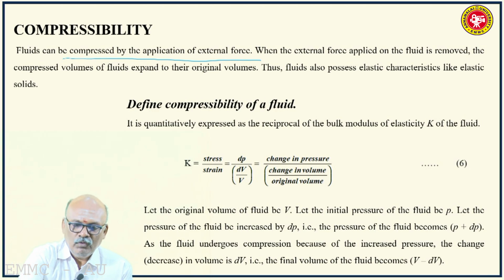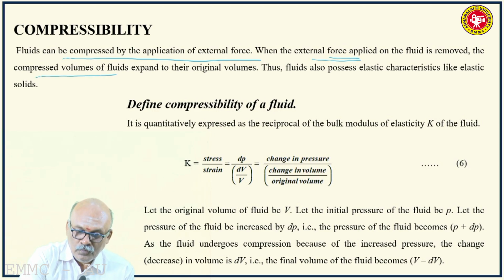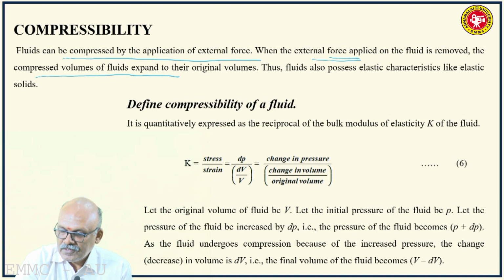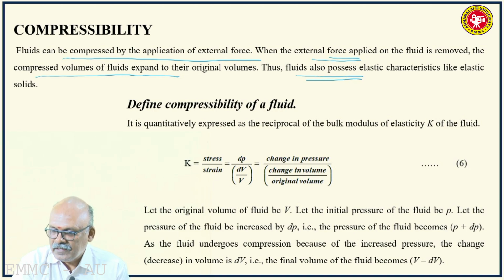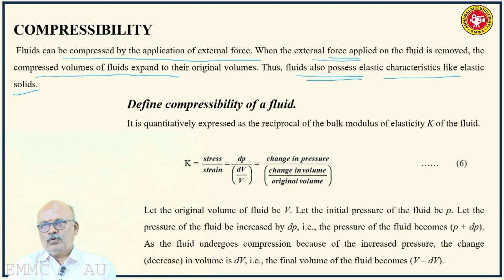So let us say the fluids can be compressed by the application of external force. Now when you remove the external force applied on the fluid, the compressed volume of the fluid expands. When the compression is released, the volume expands to the original volume. So fluids also possess elastic characteristics like elastic solids. When you release the force, the volume expands to the original volume. So let us now define the compressibility of a fluid.